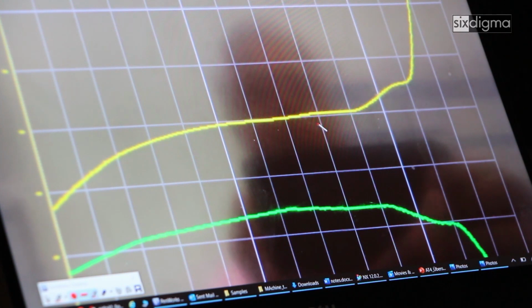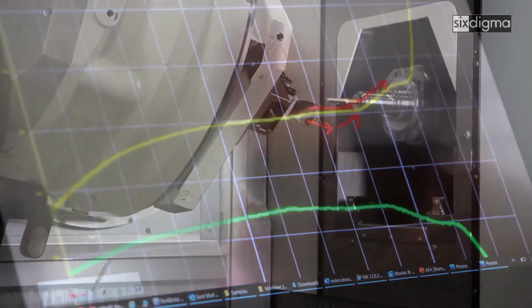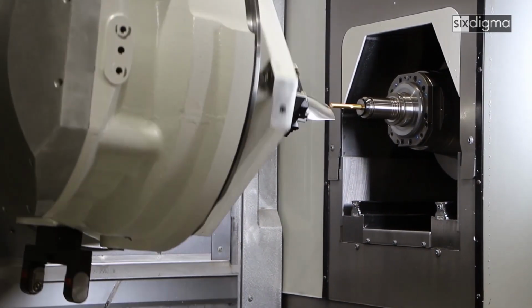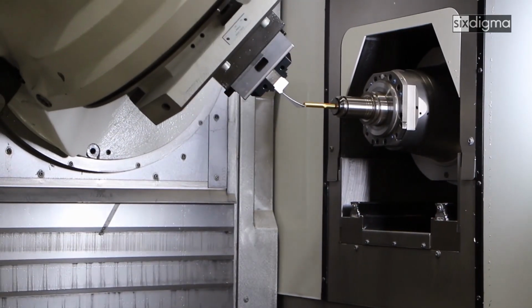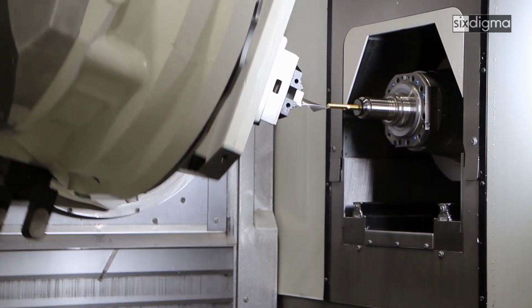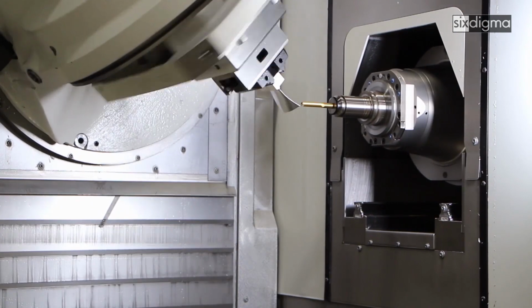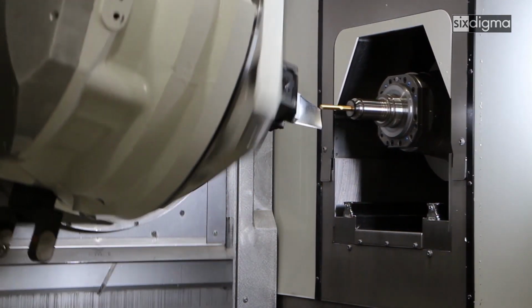In the previous example, before the correction, at this area, the graph dipped and then picked up. Here you see that we were able to correct it and continue with the positive clockwise direction of the axis, which produces a much better result. The result is a smooth surface that requires no further manual polishing. The tolerance of the part is maintained well under 1/1000th of an inch.